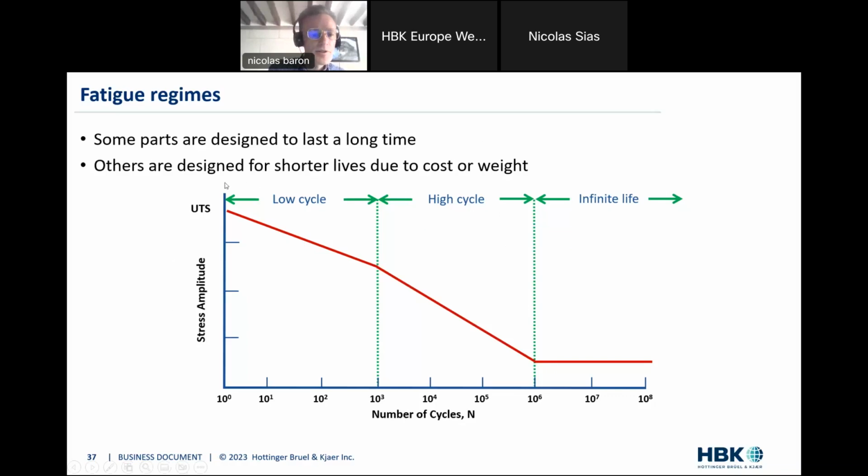And this is the first time we're seeing this sort of chart. We're going to come back to this one, but already it's interesting to notice what this represents. We have the stress amplitude on the y-axis, and we have the number of cycles, the N that I was referring to before with the S-N or the E-N methodology. This capital N stands for number of cycles. So we are graphing the stress values versus the number of cycles. How many cycles do we need for having failure at a given stress amplitude? If we are sitting on the line here, it means we are failing here. So it's just a chart, a line that relates the stress value necessary to lead to fracture at a given number of repetitions of your loading, loading forces or stresses or pressures, whatever loading you have.